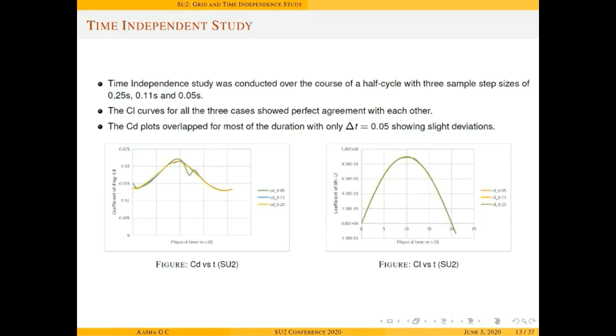Hence, time step of 0.11 second was chosen for dynamic analysis case in SU2, which translates to 10 frames for a change of 1 degree angle of attack.